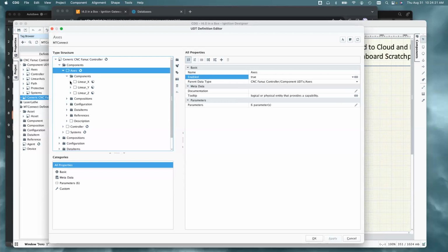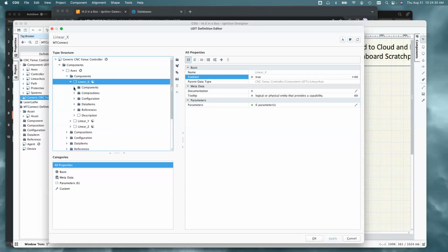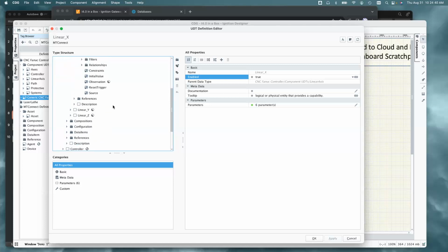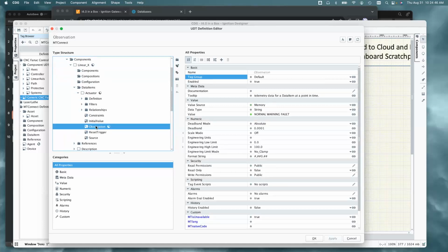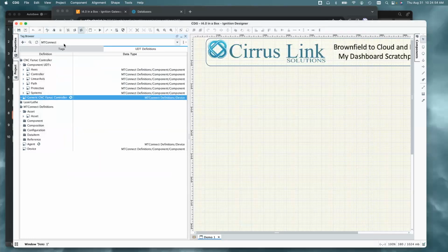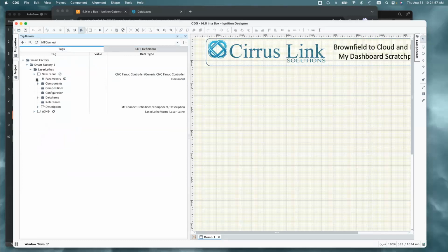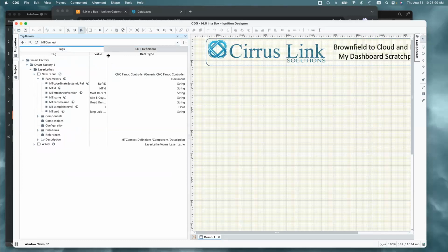So as Chris has been doing, we can iterate, we can go, that doesn't look quite right. Let's go back to the MTConnect definition, change that, then we'll pull up that new definition and reuse it up here as we start to go through some of the model definitions. So here we've got our hierarchy all the way down, as Chris had mentioned, down to the observation. Now, what that lets me do is, now that I've created the model, I can go and use the model and create my lathe and all the parameters here.